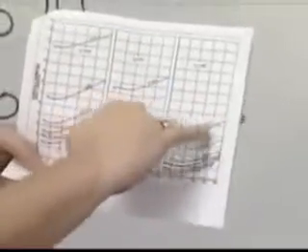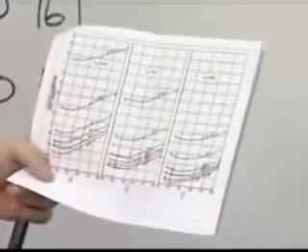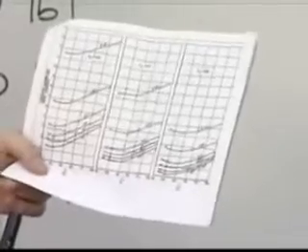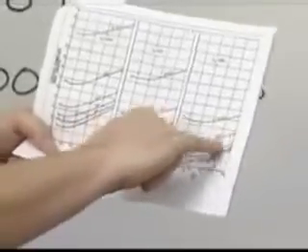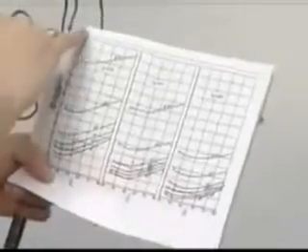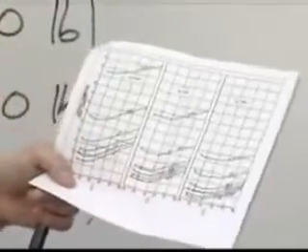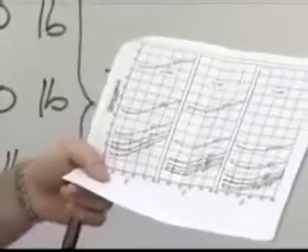Now we'll look at this family of curves in this plot. Okay? They are for different rudder deflections. We have given you in your guidelines that your rudder will be deflected to 30 degrees. And that's going to be the same for all the designs. The only line you need to look at is the line for 30 degrees. Okay? Along this axis, you'll see the turning diameter divided by ship length. You want that number to be as small as you can. That will basically mean your boat will turn the tightest.